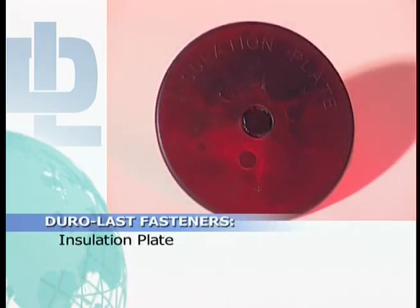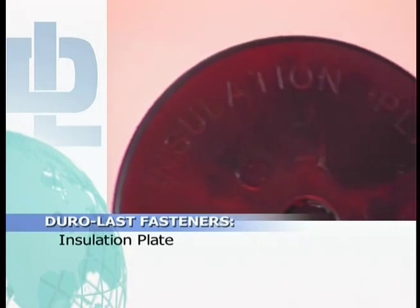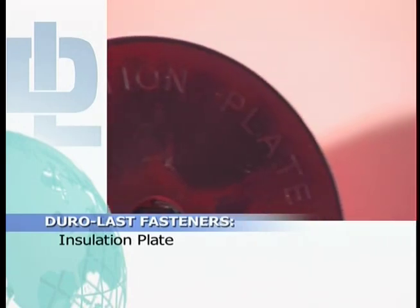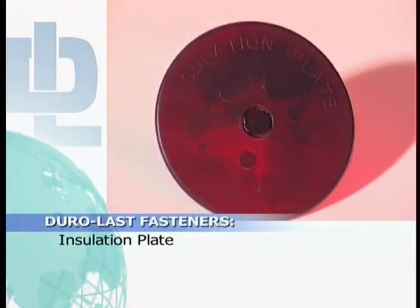The Duro-Last insulation plate is designed to be used with all Duro-Last deck fasteners except the auger fastener. This plate is 3 inches in diameter and has the words insulation plate clearly stamped on its topside. This plate can only be used with approved insulation that is mechanically attached, but at no time can it be used for roof membrane attachment.